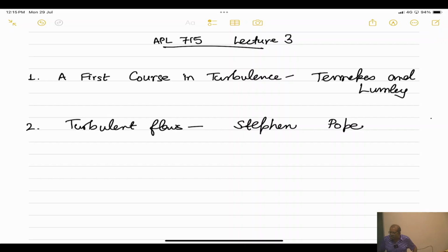In the last class, we looked at a problem where we had a length scale given to us, the length of the room, and we tried to estimate the turbulent time scales given the length scales. We talked of the ratio of the turbulent time to the molecular time. What we found was that the turbulent time scale was much less than the molecular time scale, which means mixing is much faster in a turbulent flow than in a laminar flow.